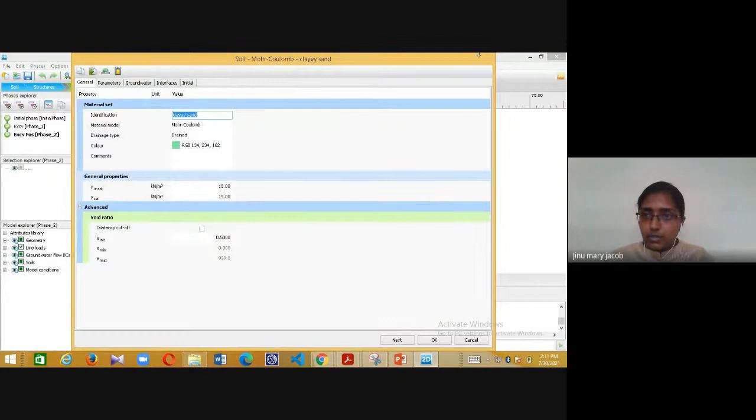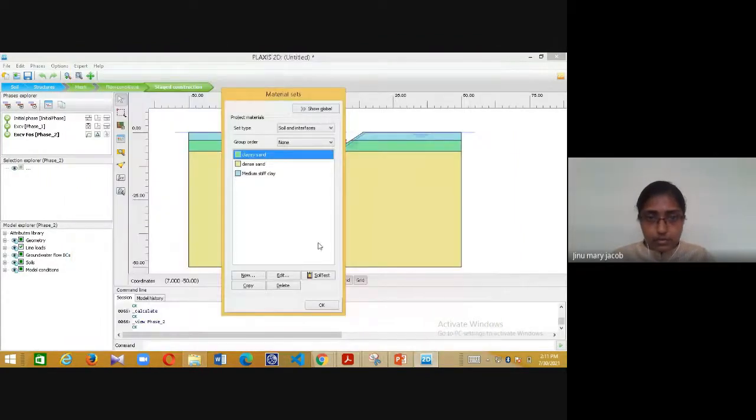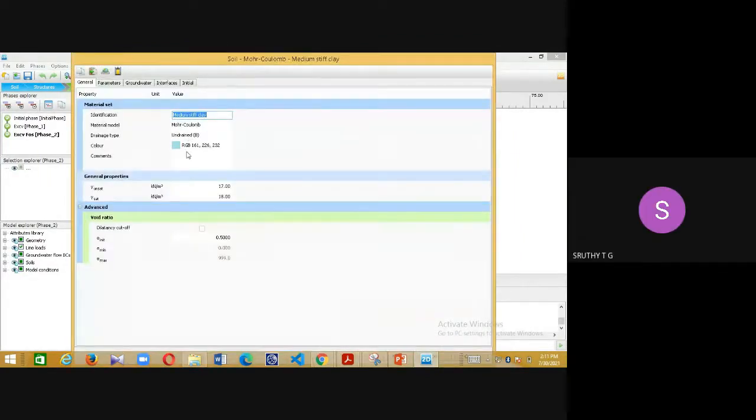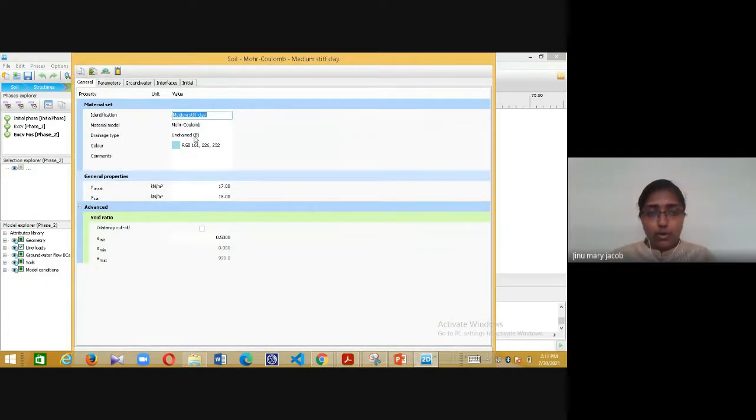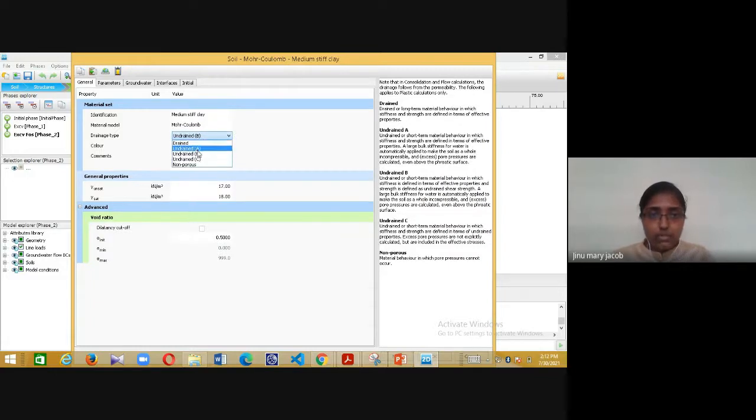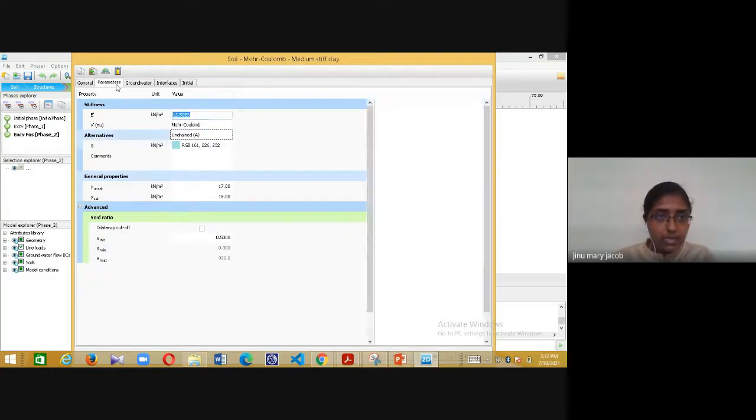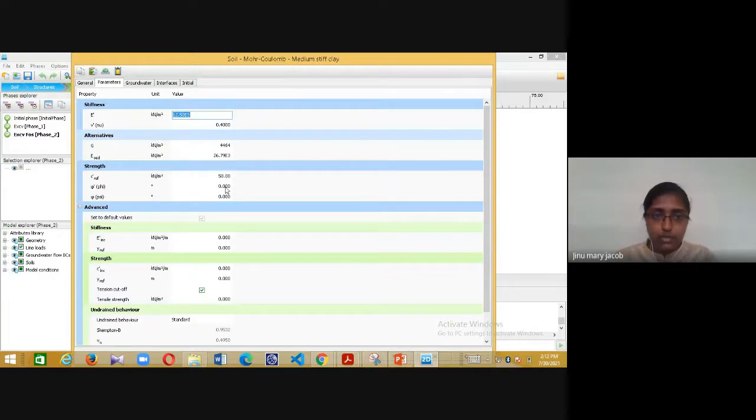Yeah, actually, for clay layer, when we define, there are two analyses, like a long-term behavior or a short-term behavior. Suppose we are having a short-term behavior, it is undrained, so it will be having only c value. Suppose it is draining for a long time and it is kept as such, then the clay layer will also, like the excess pore water pressure gets dissipated and some phi value will get generated. So in that case, we need to select, I think, undrained A. Then we have to assign a phi value also.